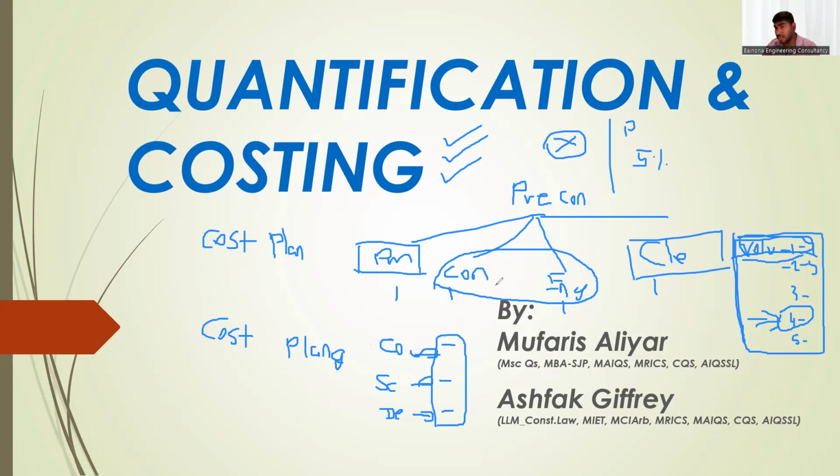Because for contractors, we know there is a cash flow. But for the client QS duty, first you need to see the construction cost plus consultancy fees, plus maybe there is a land cost, maybe legal fees, maybe other authority fees, maybe a consultant like a lift consultant, road consultant, fire consultant. So the client QS and PMC QS duty is to focus on all these things. But what is the engineer QS duty? It is mainly focused on construction cost and his own consultant cost.